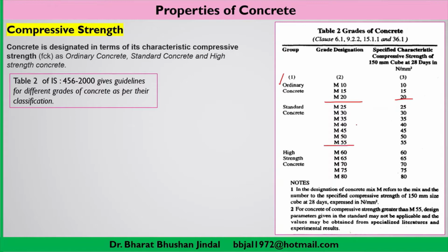Now after that, from M25 to M55, all these grades are termed as standard concrete, and correspondingly they have their compressive strength, which is known as characteristic compressive strength in MPa, that is megapascal. Beyond M55 grade of concrete, these types of concrete are known as high strength concrete.